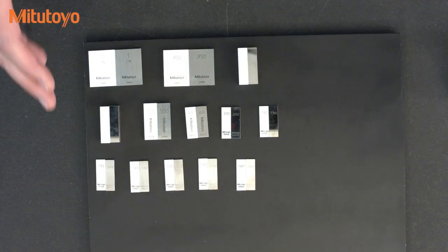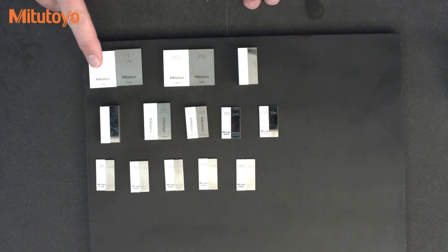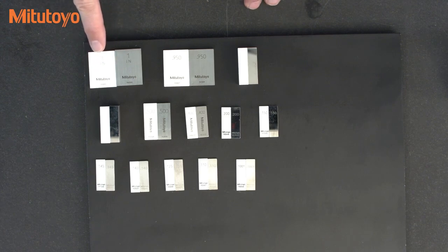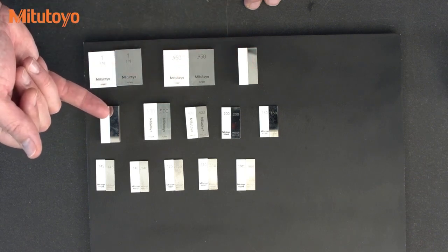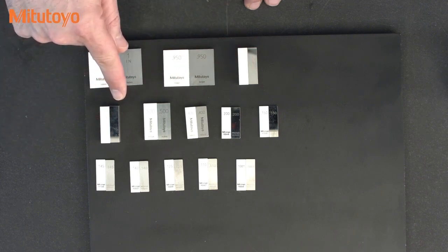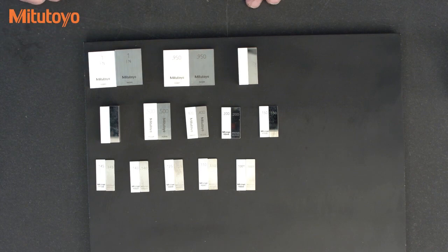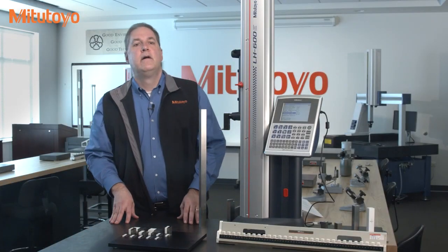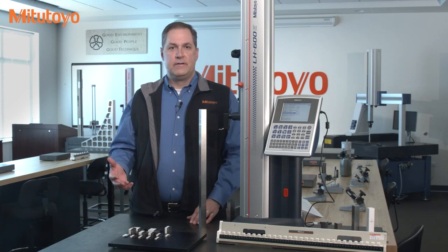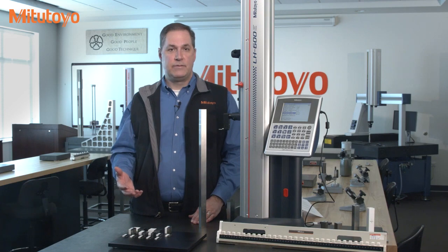Now this is an extreme example, but when calibrating gauge blocks, we arrange the customer's gauge blocks, which are the white ceramic ones here, one by one next to our master blocks, these steel ones here. The goal is to have the two blocks be at the same temperature. We also use this aluminum plate to help with the heat transfer. If you have a stable environment and things thermally soak out properly, you've taken care of many temperature problems.